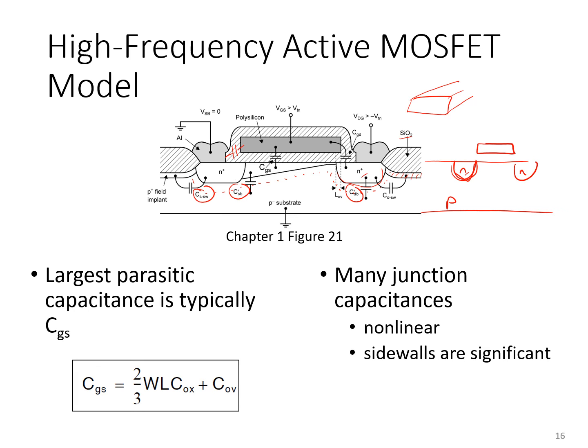One of which is to introduce, as depicted here, a sort of extra insulating layer, and another technique is to introduce a heavily doped layer. Now, this has an important impact on parasitic capacitances because a heavily doped region forms a heavily doped PN junction here, which therefore has a higher reverse bias capacitance. So you end up with a component of the parasitic capacitance of the drain that depends on how long the edge of this drain region is, okay?